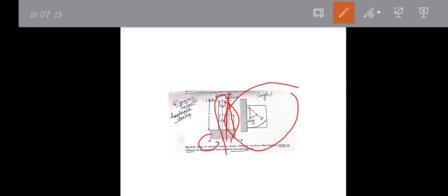Some energy is absorbed by the deformation, and the remaining energy produces the rebound. The direction of the rebound makes an angle with the vertical, known as the angle of rebound. In this method, a carbide ball of 3 mm diameter is used as the indenter. After the release of the preloaded spring, the indenter is thrust against the test specimen.